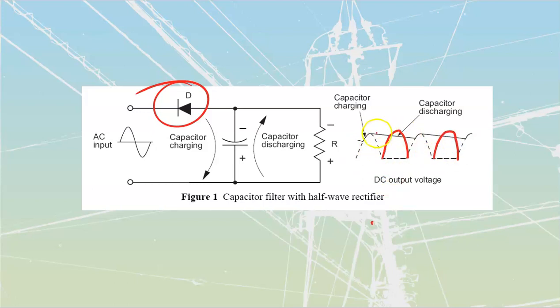And if it's on a full-wave rectified circuit, we're actually going to have a much better voltage regulation, because we see that this peak over here picks that back up right over there, and it never gets down quite as low. So we will see caps used on the full-wave rectified circuits as well.